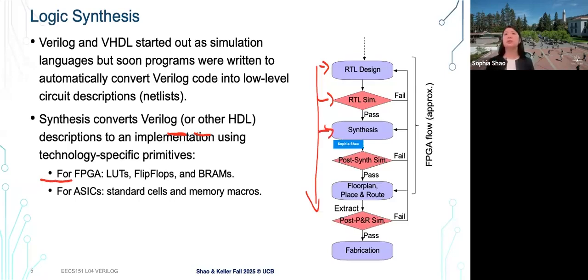After that, you want to do the synthesis. We'll get to the gate level representation to see how your hardware gets synthesized into the particular technology node. Of course, this is a very iterative process. Whenever you have a new representation, you always do more simulation to make sure it behaves as expected. As we get to the lower level, you factor in more realistic components.